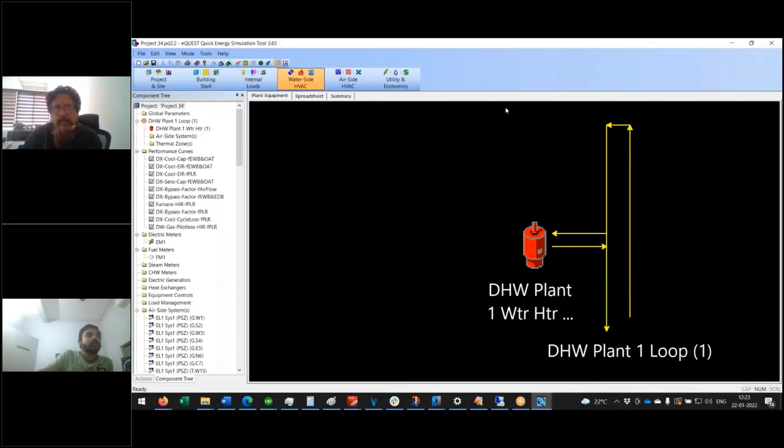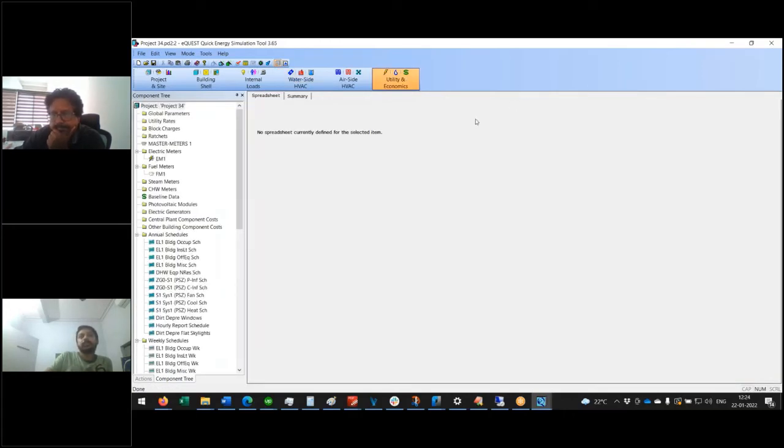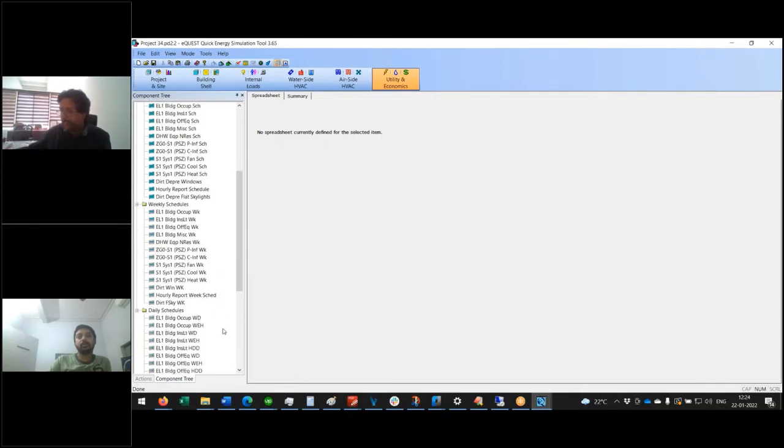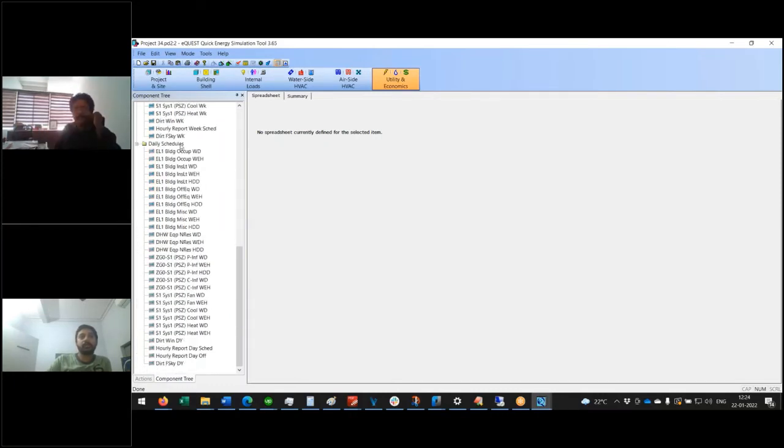Okay, so question here from Mr. Philip is, how do we enter the exterior lighting? So exterior lighting is a direct load on the meter. So all you have to do is create an external lighting schedule. Okay, let me create one here.